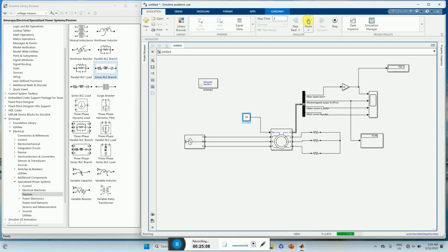So the thing is that this rotor resistance, if it exceeds a certain value, the motor may not run in the forward direction, it may reverse, just like an active load. Maybe the starting jerk that is required is not there, so it will create a problem. So that's why this resistance is to be chosen carefully.